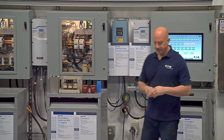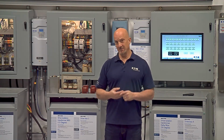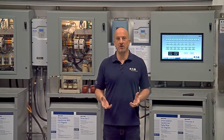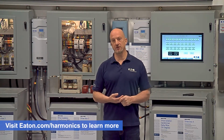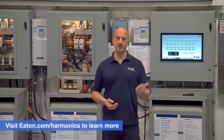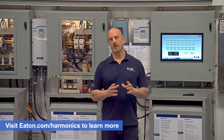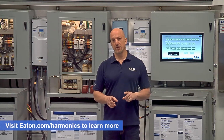So again, as we look at generators and harmonics, what's important to know? The impedance is going to be significantly higher than my normal utility source. So how can I get rid of the harmonic voltage distortion? I could turn off my load, but that's not always a great option. If I have to run my VFDs and other harmonic producing loads on my generator, I might have to filter that current so that I don't distort the voltage. And oftentimes that's the answer: filtering the current or putting in phase shifting transformers or some other method of minimizing the harmonic currents on the system so that I don't distort the voltage no matter which source I'm on.